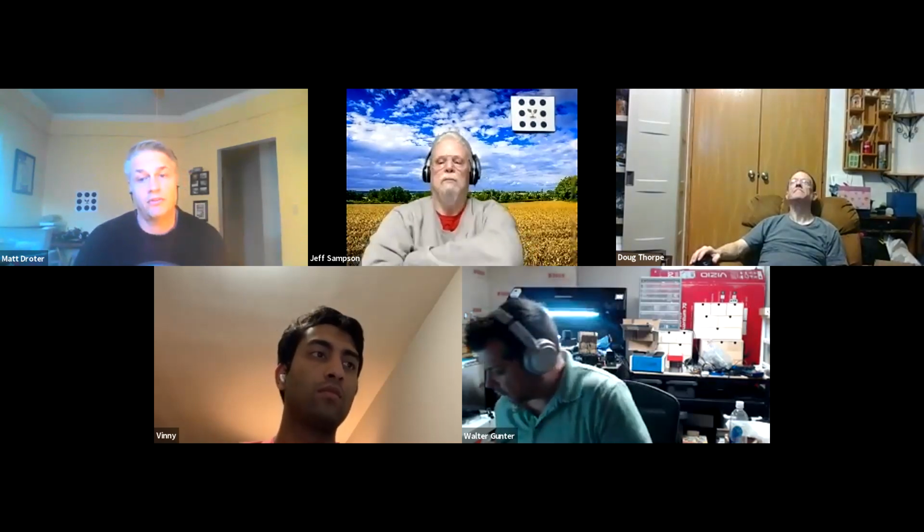So are those GPS coordinates fed into the fake GPS topic in the sim? No, so ROS uses Cartesian coordinates from an origin, and we were kind of interested in the GPS data at one point, so basically I just took the odometry message from the simulator and then converted that into lat long, and then published that message out as a GPS message. So even in simulation, you could have a GPS message to learn from and to use. Okay.